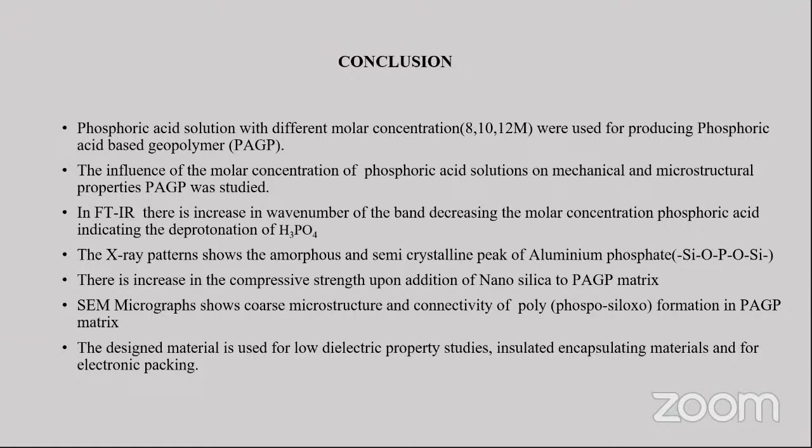So, conclusion: phosphoric acid solutions with different molar ratios were prepared and used for phosphoric acid-based geopolymer. The influence of the molar concentration of phosphoric acid solutions on the mechanical and microstructural properties was studied. The FTIR shows an increase in the wave number of the band with decreasing molar concentration, indicating the deprotonation of orthophosphoric acid. The X-ray pattern shows the amorphous and semi-crystalline peak of aluminum phosphate.